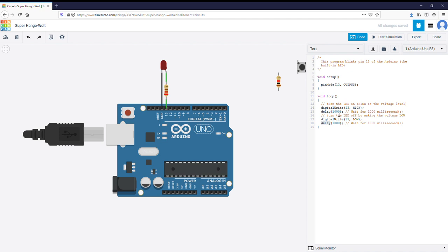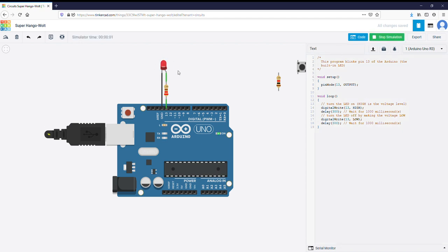And you can just test. Say, let's make it 500, so it's not going to be 1 second but 0.5. Let's make it even shorter, 0.3. Then this should blink faster. You can see that this is blinking, blink, blink, blink, at 0.3 seconds.